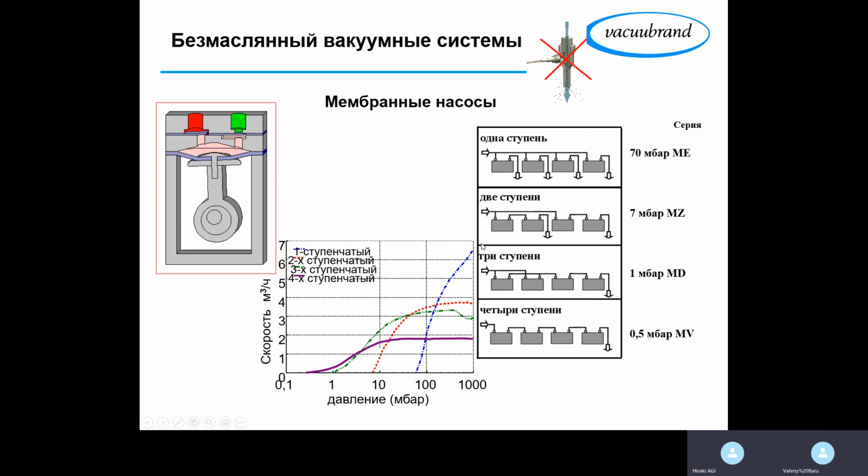So that is why actually we have lower performance but a higher vacuum, because in the one stage pump all the chambers are pumping out simultaneously, and so you can pump out more gas at the same time. But in case we have a two-stage pump, the second stage works as the fore vacuum pump.